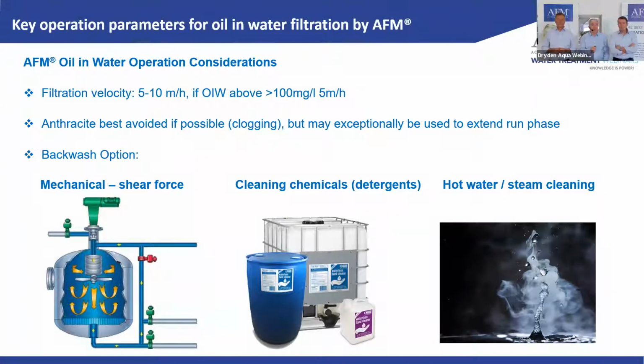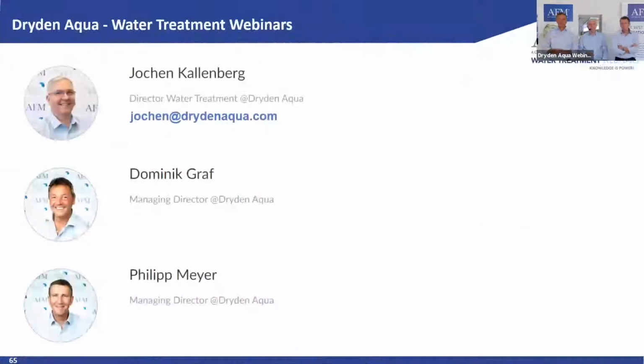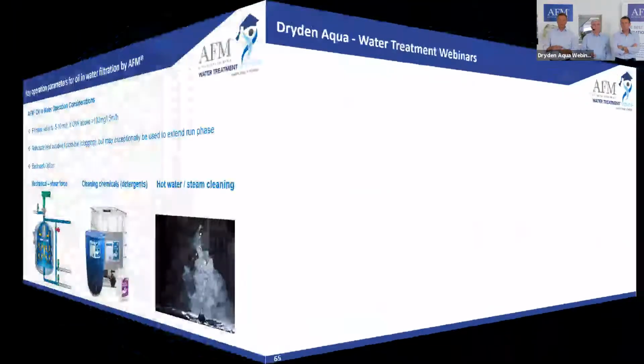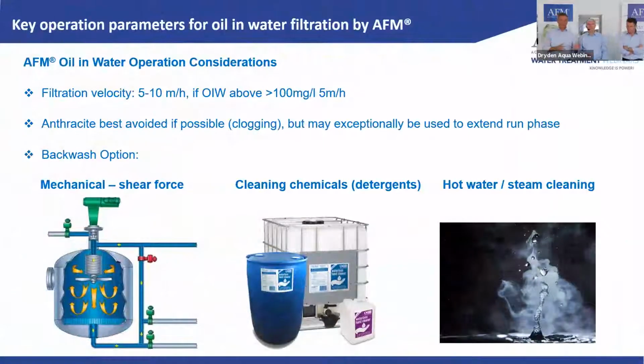Yes, very important. Just to summarize, AFM performs much better than nutshells, which is one of the key products used in these applications. And usually in these applications, we use AFM standard. It's not because it filters better than nutshell, it's the opposite, but it's easier to clean.